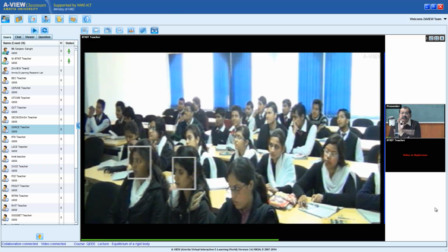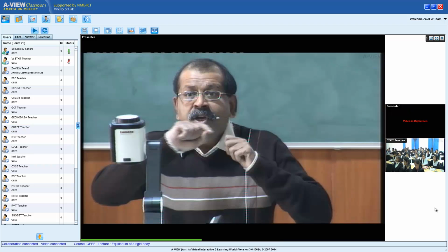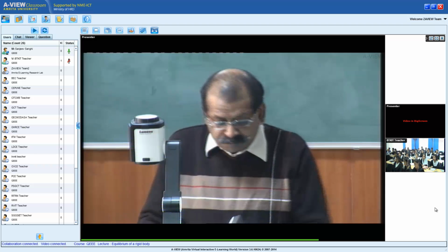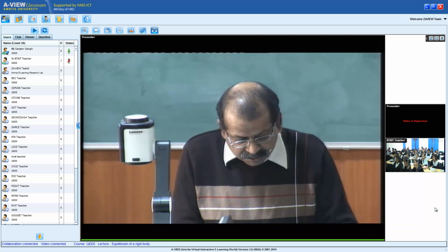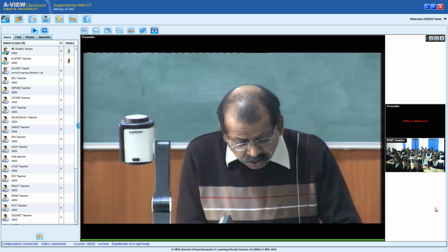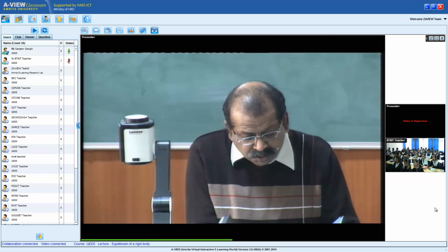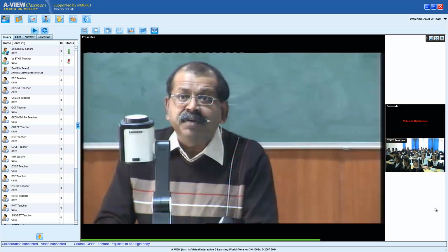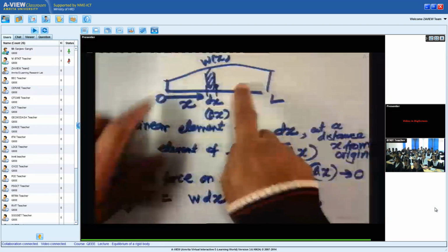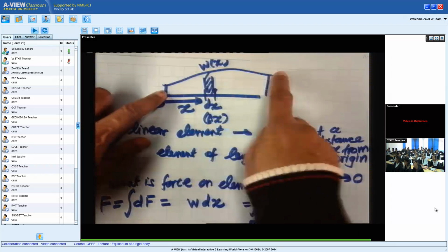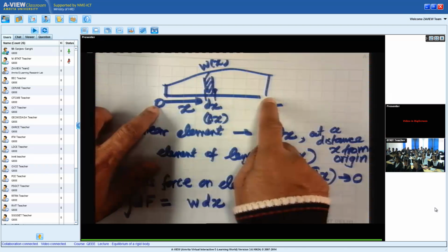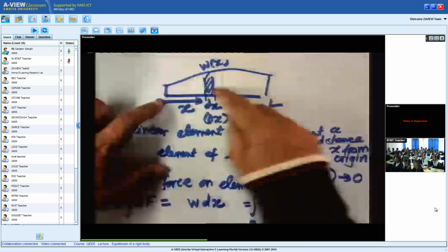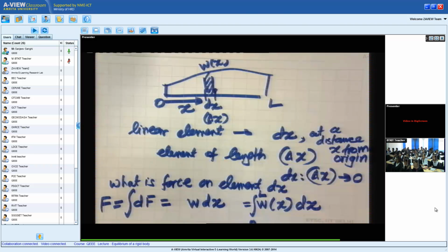No, I said this for a linearly distributed force, a force which varies along a line. So see what I showed to you in the figure. Let me just get back to that figure. What I explained was for a linearly varying force. If a linearly varying force is acting along a line, then what I said was the area under the loading curve gives the effective force.